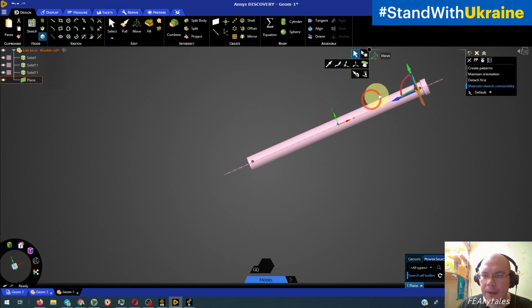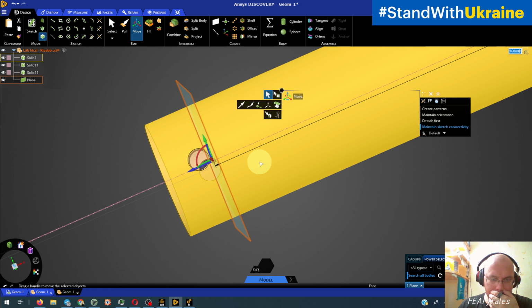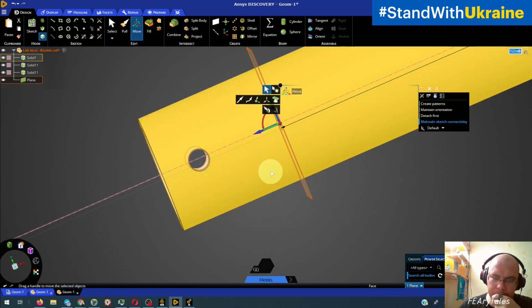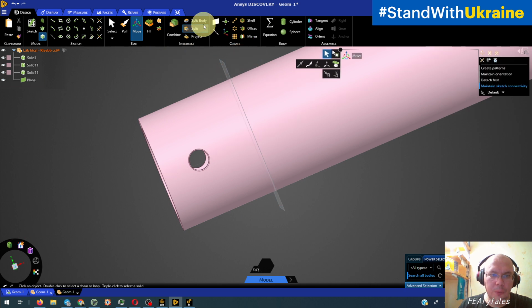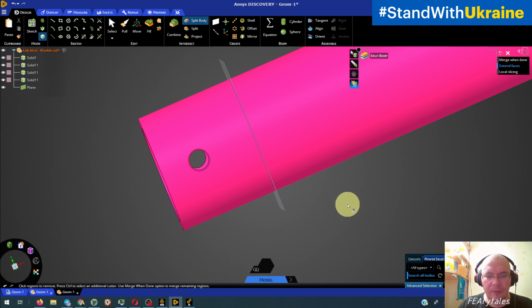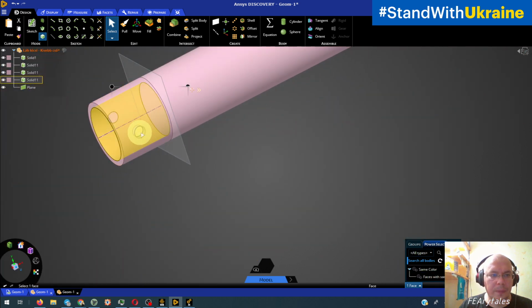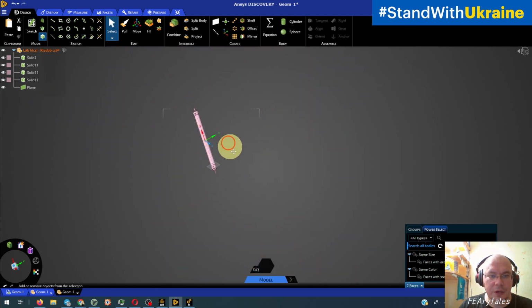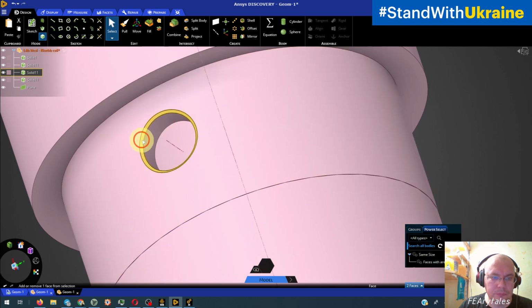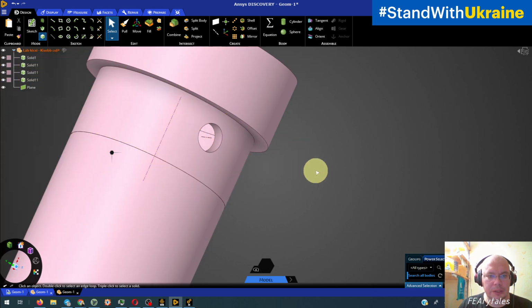Move this one up to, for example, here. We split those bodies with this one, and also we select all these chamfers and delete them.